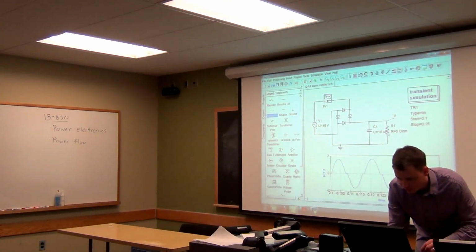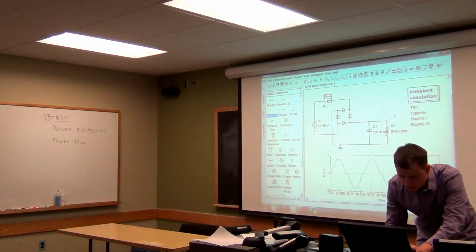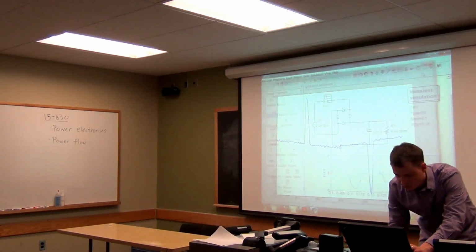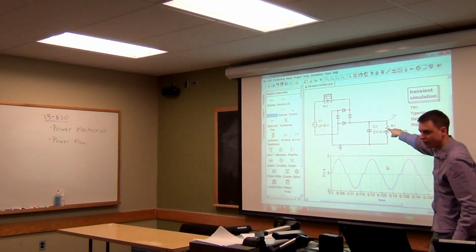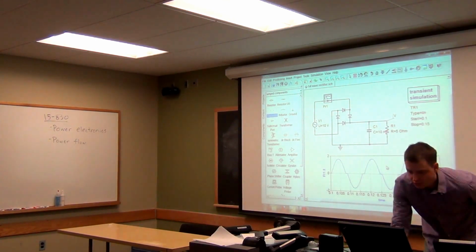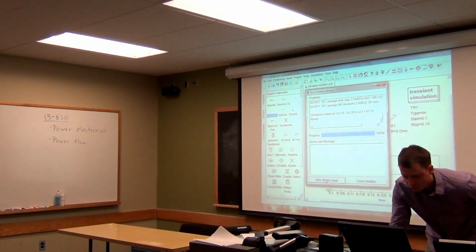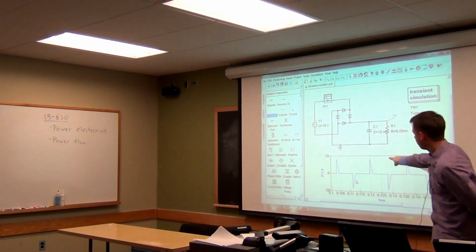Let me put the capacitor back in. Let me close this. So this is a system where there's no switch involved. These are just rectifiers and capacitors here. I run this simulation, and what you get in the current waveform is exactly this.